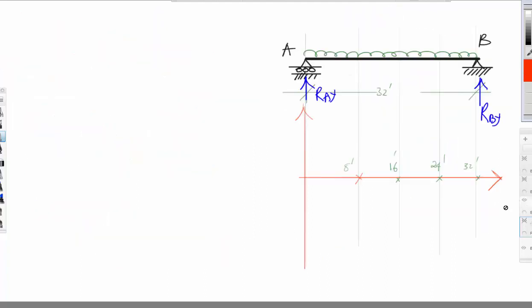work on the shear force diagram. So for shear force diagram, this is not like the point load. In the case of point load, it was straightforward, you didn't need any calculation, but in this case we'll need calculation, and this is 3 kip per foot. And like we said, this uniform load is as if it is 3 kips at each point.